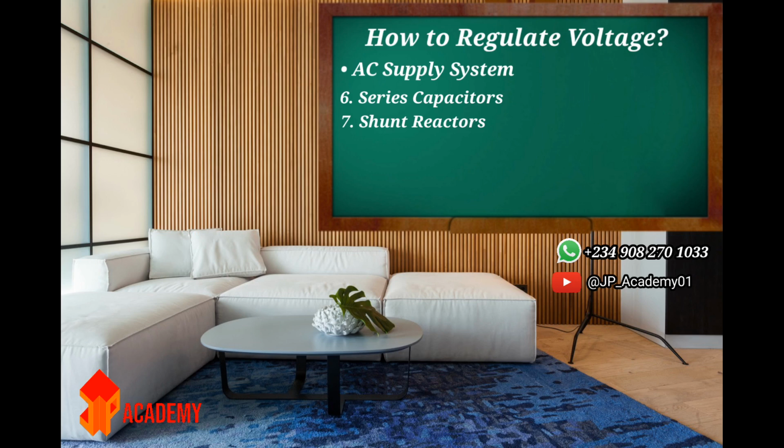The next method is switching in shunt capacitors during high load or low power factor load, and they are installed near the load terminals, in factory substations, in the receiving substations, and in switching substations.